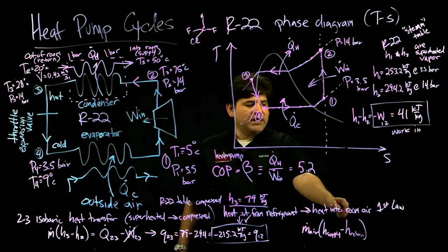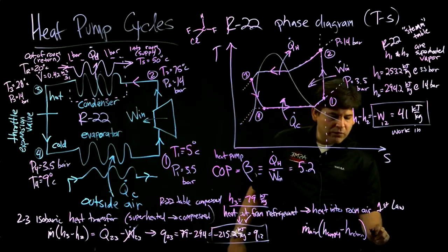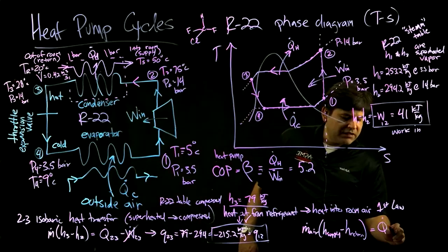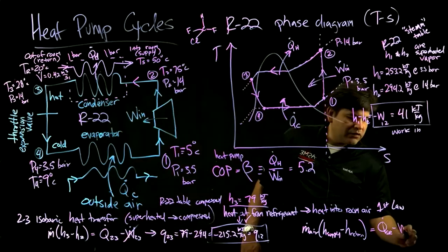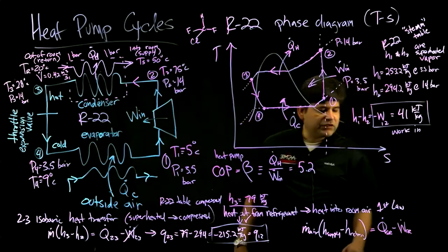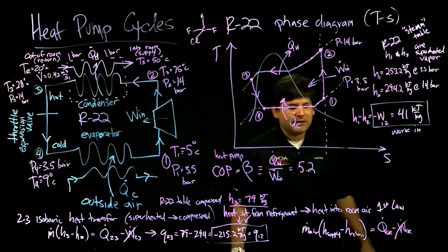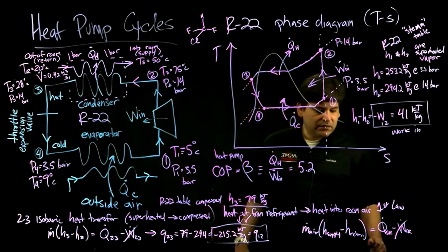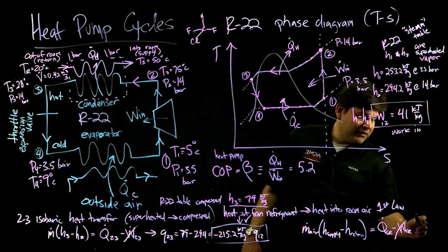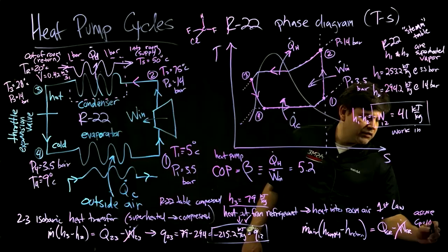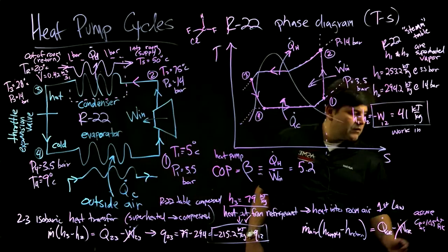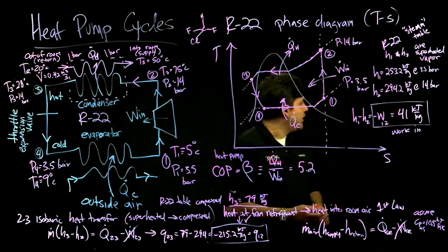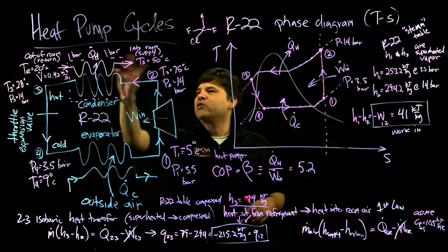So focusing on the room air, this has to balance out with some heat transfer and work transfer, supply versus room. This is just a heat exchanger, so it's just that. And we could have made another assumption, assuming Cp equals 1.005 kilojoules per kilogram Kelvin, which is a reasonable approximation at this temperature change, only 30 degrees Celsius.